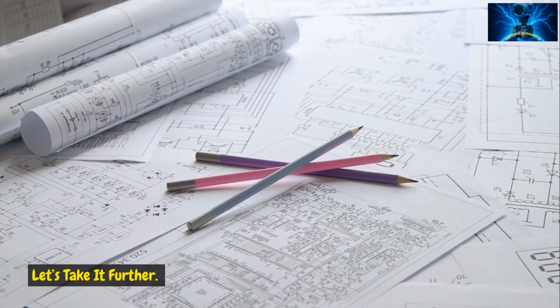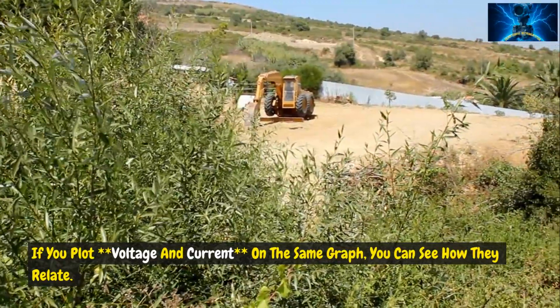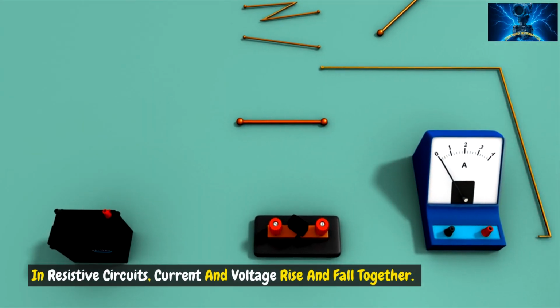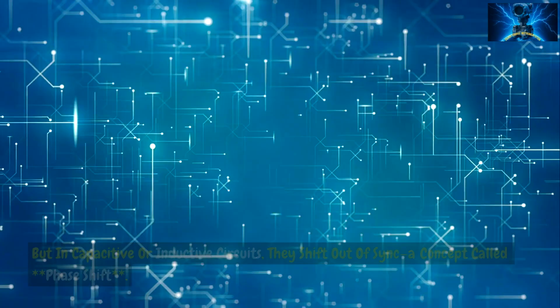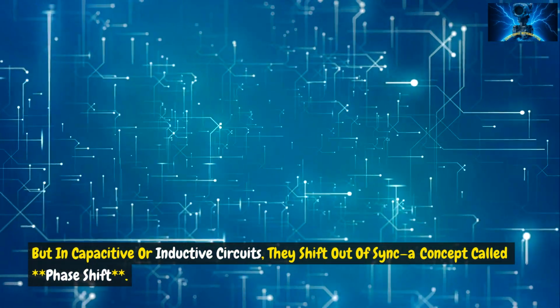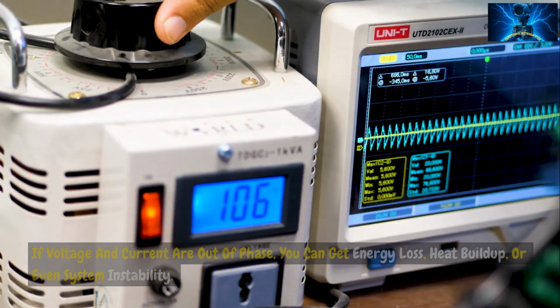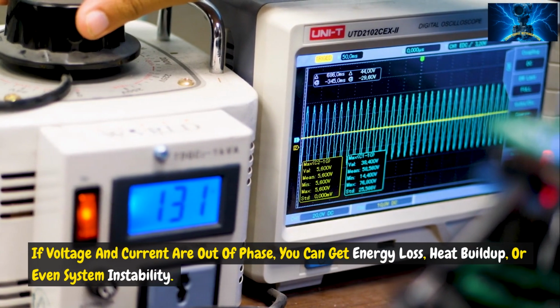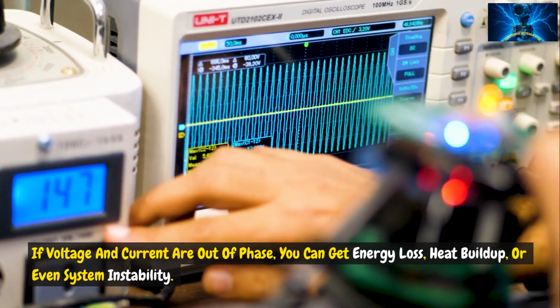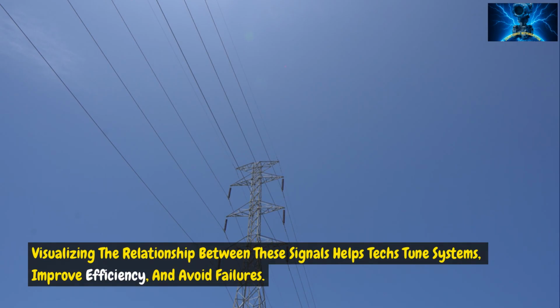Let's take it further. If you plot voltage and current on the same graph, you can see how they relate. In resistive circuits, current and voltage rise and fall together. But in capacitive or inductive circuits, they shift out of sync, a concept called phase shift. This is critical in real systems. If voltage and current are out of phase, you can get energy loss, heat buildup, or even system instability. Visualizing the relationship between these signals helps techs tune systems, improve efficiency, and avoid failures.